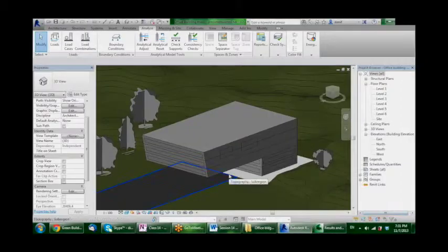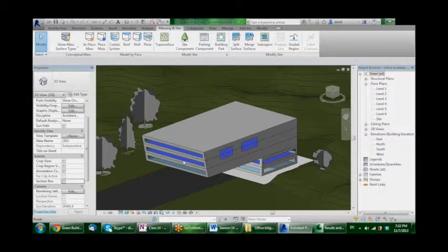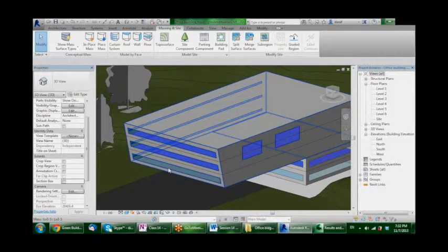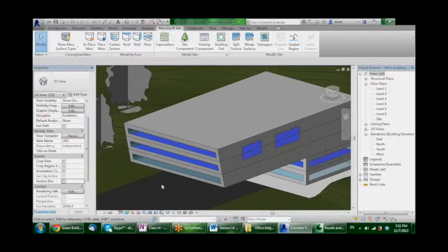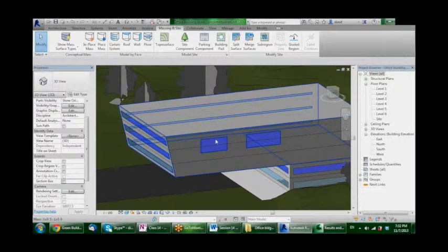Okay. To the second question about the windows. At this point, you're wavering between two areas, architecture and function, and energy analysis. What I meant by it's not the right point to customize glazing is that you should think about your openings, but it's not the appropriate time to go ahead and fully customize them. So let's say I made a square here, but when I finish the design, this might be an L-shaped window, for example. You understand?